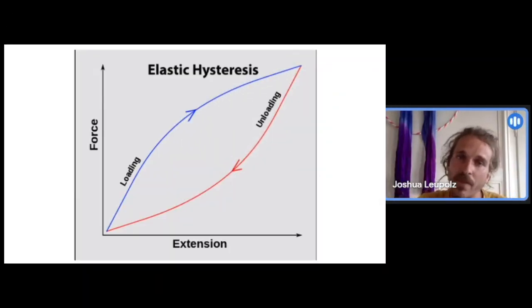So it's always going up and always going down. If you record this curve, you have the force in the lower corner, 2 kilonewton up to 5 kilonewton, and then you measure on this side the extension, and you have the path going up and down, and then you get a lot of interesting information out of this. First of all, the extension, which is really interesting. This can then be transferred to percentage.